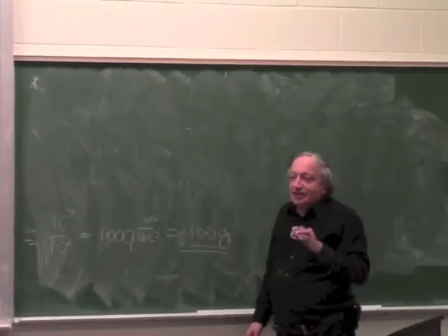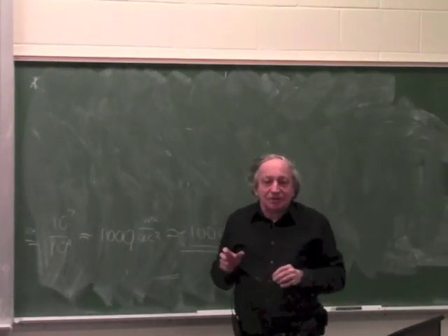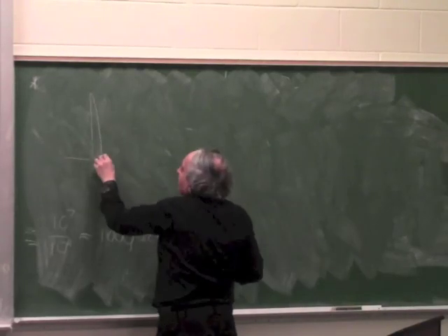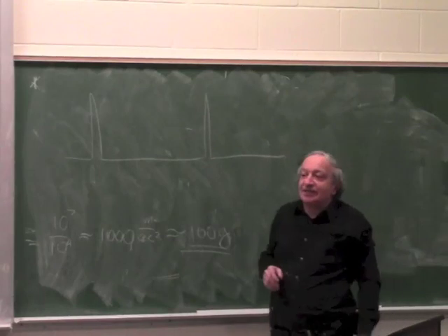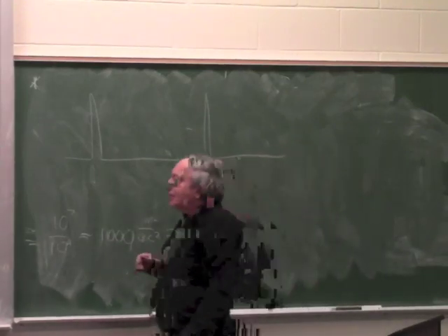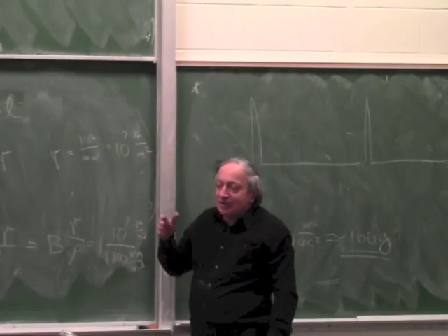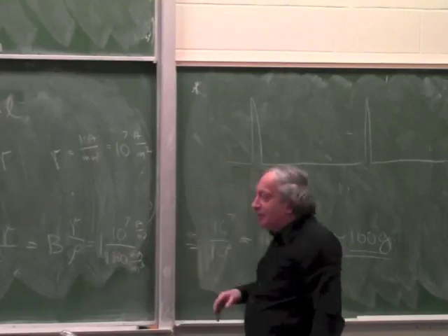Okay, so first I keep reminding you, this is for continuous operation. If I need an actuator which just has to move a pulse and then wait, move a pulse and then wait, then what I really care about is the average heating, or to be more accurate, the RMS, not the average, and we'll talk about it later.